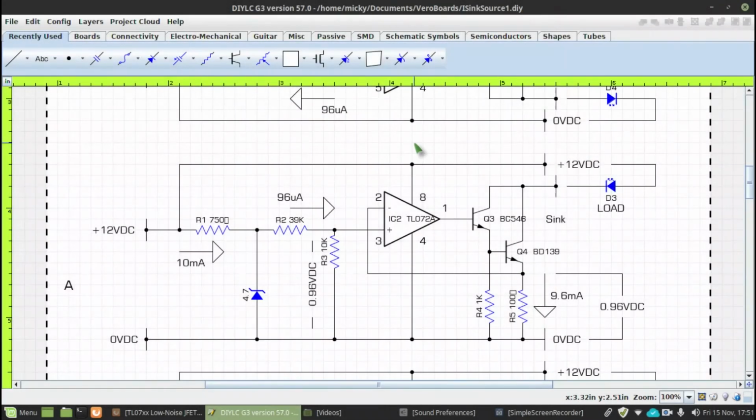I thought today we would explore the landscape of an op-amp. I particularly like this op-amp. There is, of course, a whole myriad of op-amps, but this one I've got to know over the years, and it's the TL072A op-amp with a JFET input, so very high impedance.